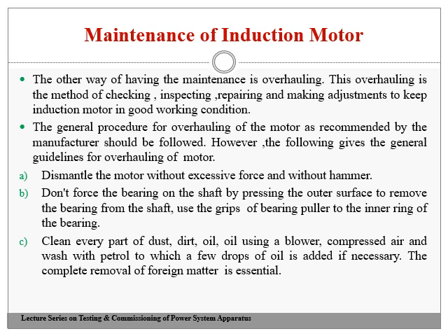Clean every part of the induction motor for dirt and oil using a blower or compressed air, and wash with petrol to which a few drops of oil are added if necessary.